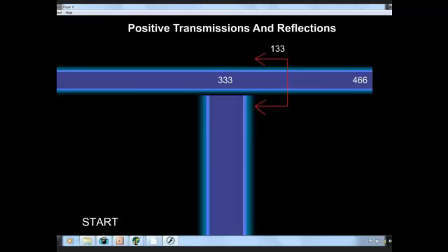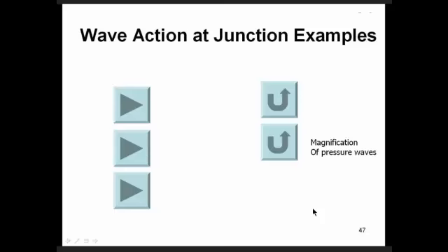foot increase in pressure. So dead ends in pipes, large pipes going into small pipes, are very significant. That is sort of at odds with the idea that you can get rid of all your smaller pipes when you do surge analysis. Because if you're going from 12 into a 6 and a 6 into a 3, you could end up getting some very high pressures in those smaller pipelines.